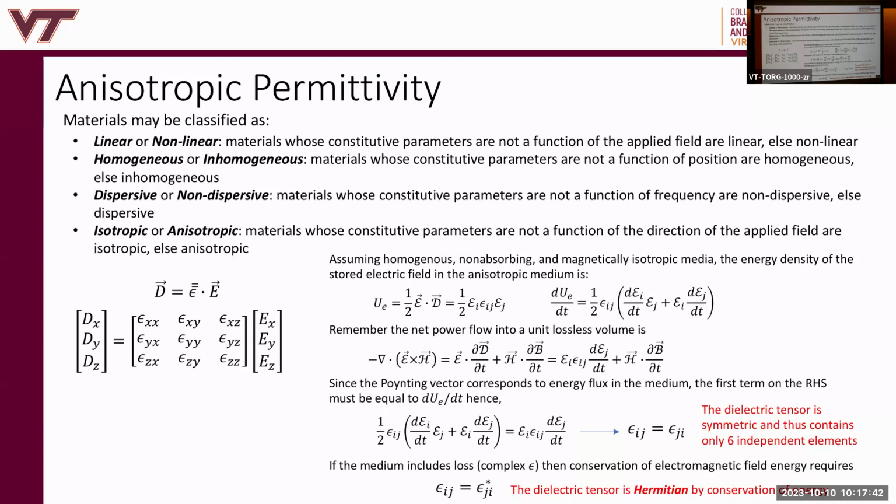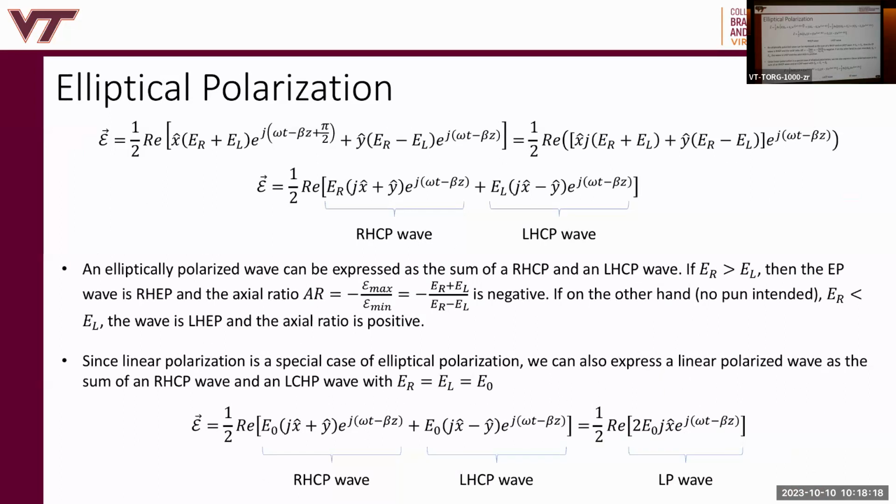And then say you design a metasurface, for example. I design a metasurface where I come in with a particular polarization, and I can convert that into circular polarization upon transmission through the metasurface. If you do that in optics, there are things called wave plates, and they have a certain thickness to them, right? They have to be a quarter wave thick, and you can convert LP to CP if you have the right wave plate. But in metasurfaces, you could do that at the interface, the boundary, right? And you can design a metasurface to impose that last expression. Remember, LP can be considered as RHCP and LHCP. You can do something like this. You need an anisotropic metasurface in order to do that.